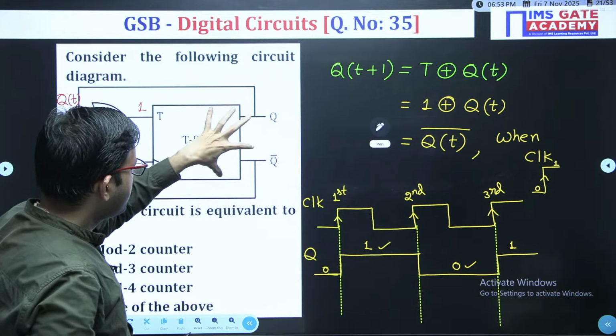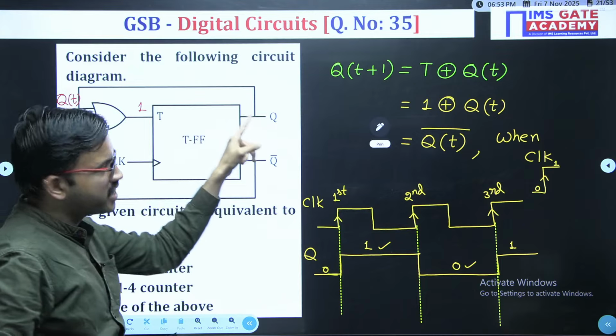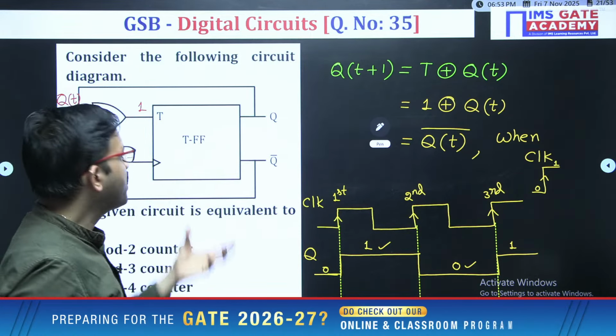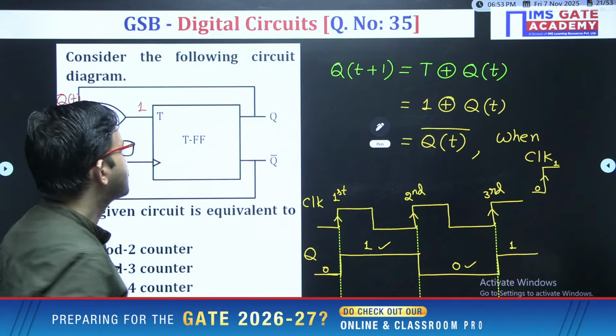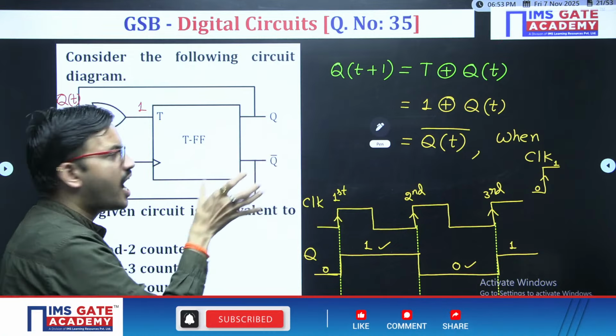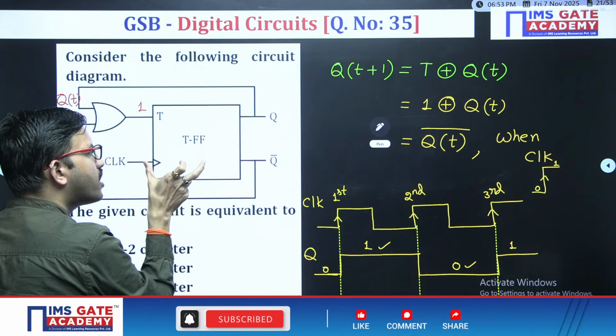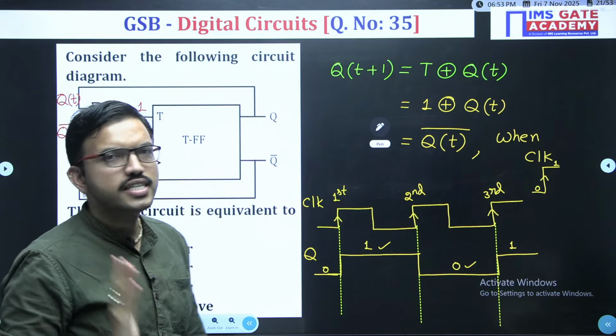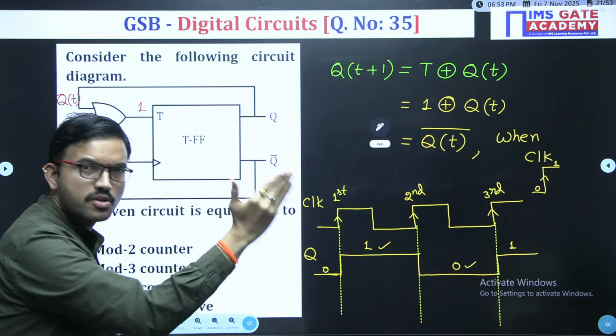If the flip-flop is ideal, you get the output immediately when the positive edge is given. But just like a logic gate, the flip-flop has a delay. That means each and every flip-flop produces its output after its individual flip-flop delay. That is the meaning of synchronous: every flip-flop has the same clock signal.